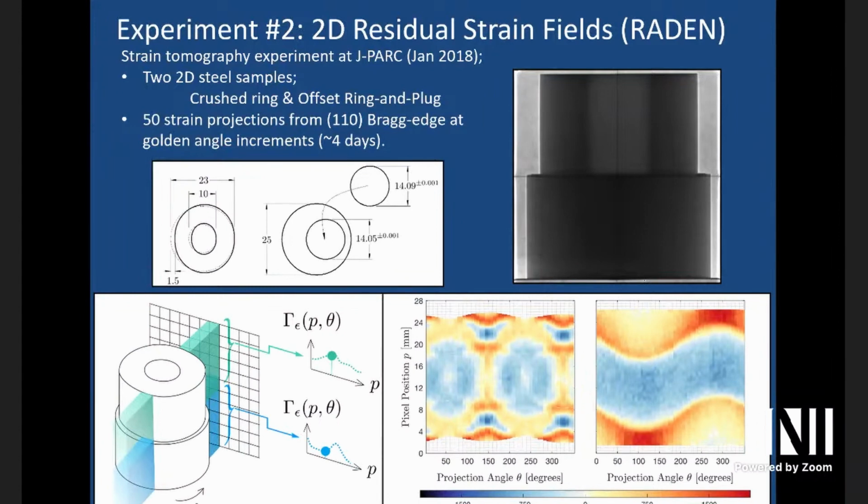So you get a piece of steel, you drill a very precise hole in it with very high tolerance, and then you make another piece of steel out of the same piece that is ever so slightly too big for the hole. Once again, surface ground and very precisely controlled dimensions. Then you put the big ring in the oven, and you put the little plug in liquid nitrogen, and you quickly put them together, and everything becomes happy, and you've built in some stress, right? So the plug is too big for the hole that it's in, and that's a form of residual stress.